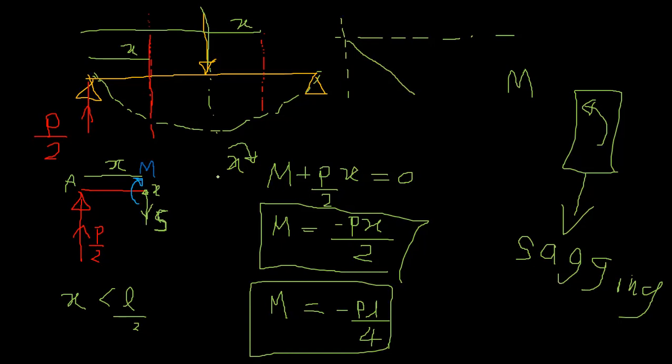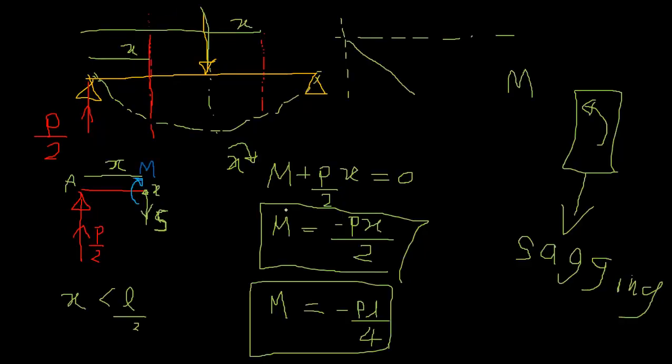You can determine again from this. So you need to write another equation because there's a point load active here, so your equation should change. Let's consider that as well, and we would cut here. That's a point load, P over 2, P, and here it's X. So you can write the summation of forces in y direction as well.